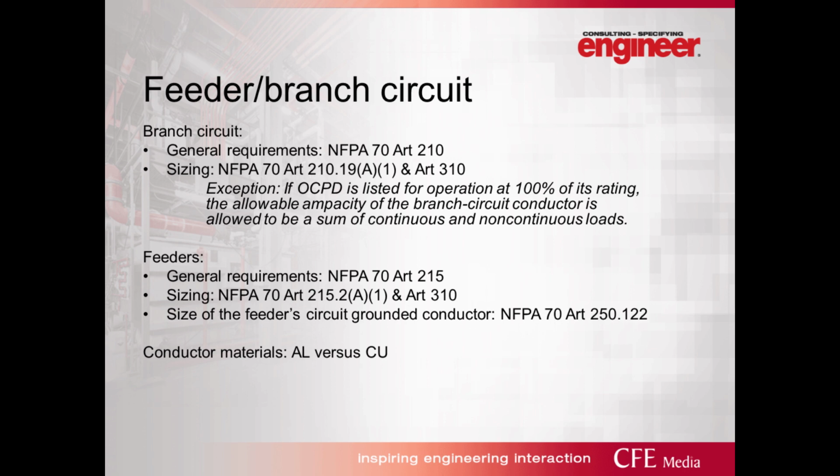For sizing conductors in a low voltage system, we use Table 310.15(B)(16). Materials, copper versus aluminum. Weight, electrical capacity, and cost are major considerations when selecting aluminum or copper for an electrical application. Copper offers a better electrical capacity per volume.